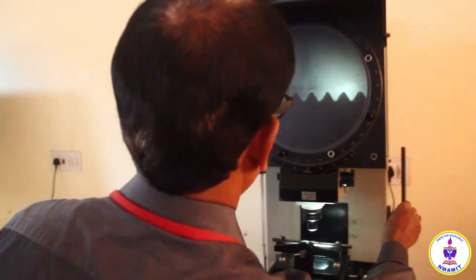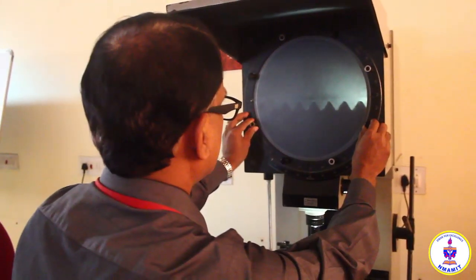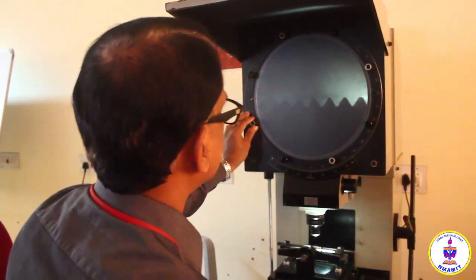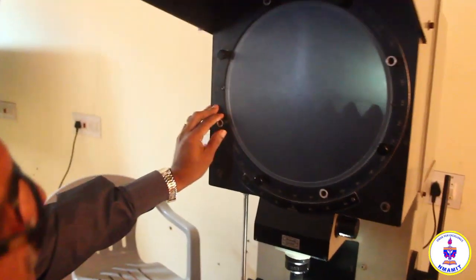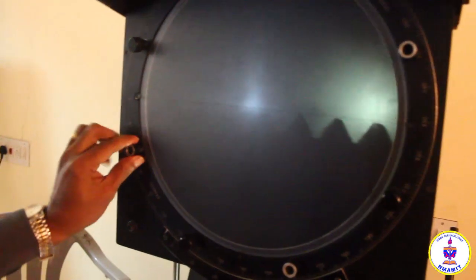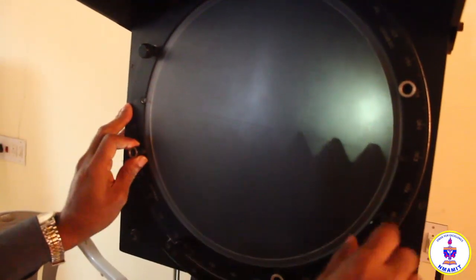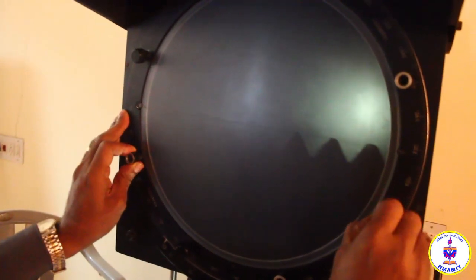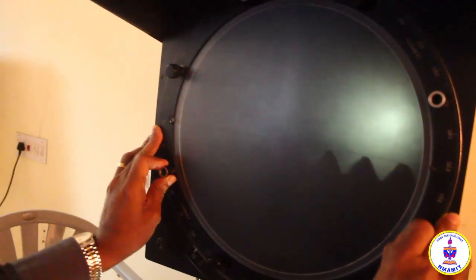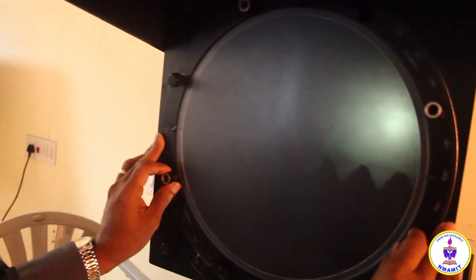Okay, now we have got a fairly sharp image of the screw thread. Now in order to make the measurement here, adjust the micrometer so that the horizontal cross wire is parallel to the threads. This screen has two cross lines, a vertical and a horizontal one. You adjust the horizontal cross line so that it is brought parallel to the threads, say more than 3 or 4 threads here.